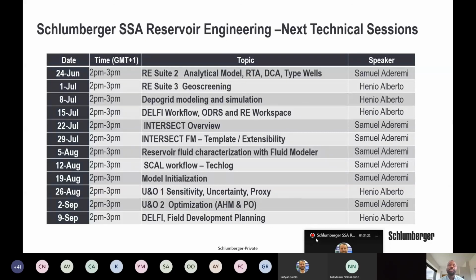But from the material balance itself in Petrel, there's not yet the forecast, only the tank model generation and the calibration process, which allows you to refine and optimize using an uncertainty engine. This will give you the tools and the parameters which you then use to optimize your numerical simulator.